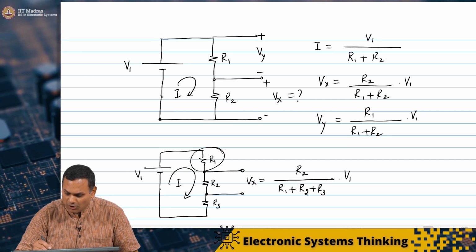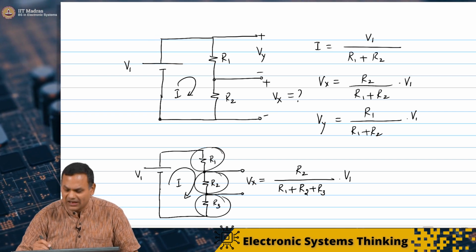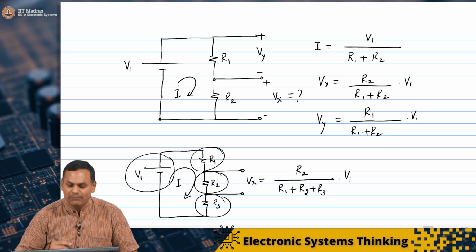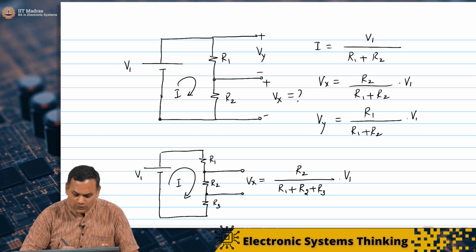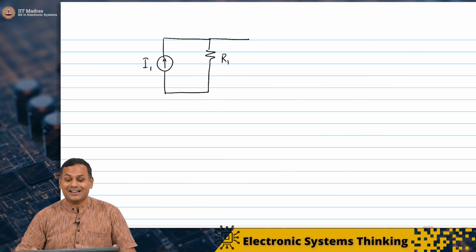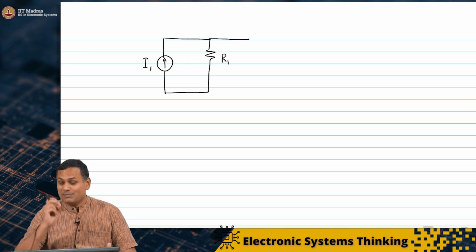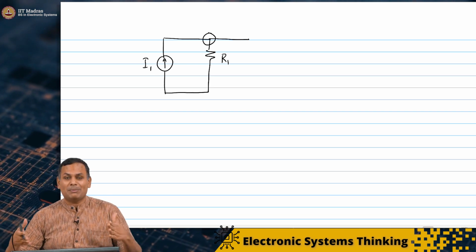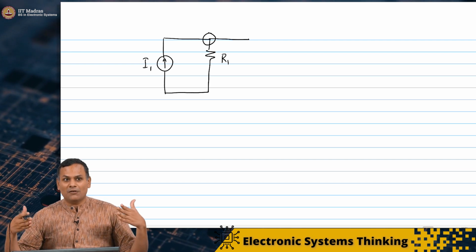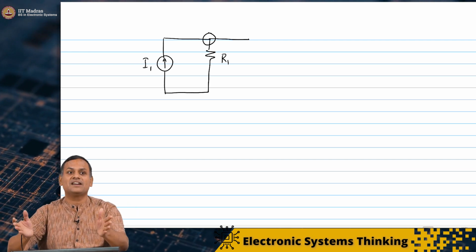the sum of the voltage drops across R1, R2, R3 is equal to the input voltage V1, you can say that there needs to exist a similar property for currents, except remember that currents distribute across nodes. So, remember, you apply KCL: the sum of currents entering the node is equal to the sum of the currents leaving the node.